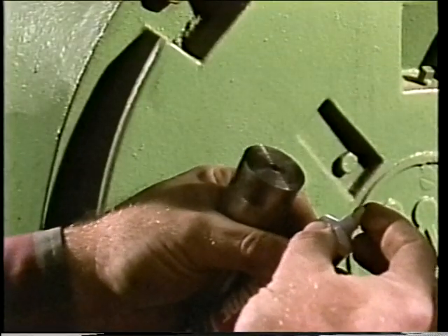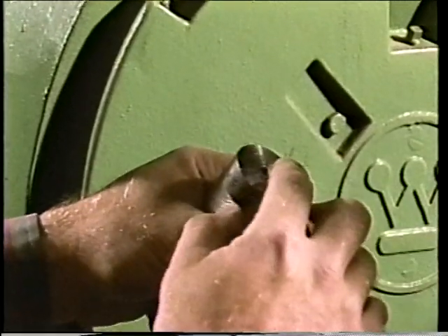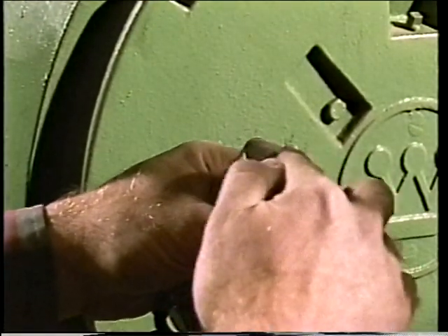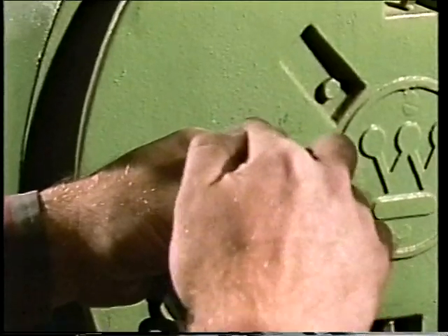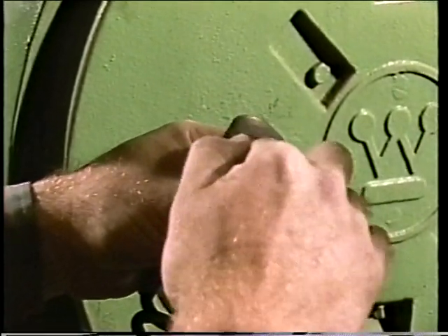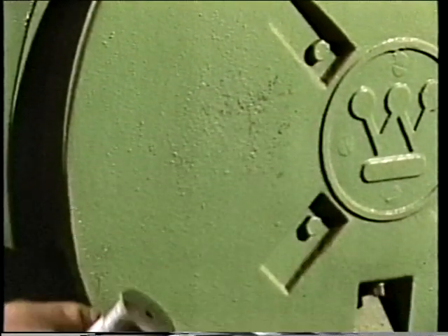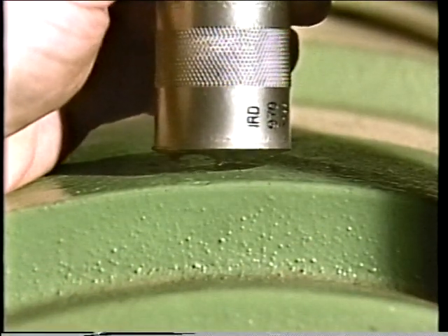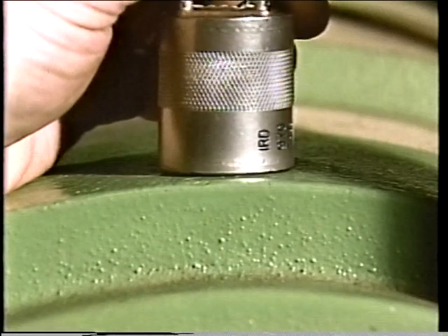In addition, many pickup manufacturers recommend using a silicone grease between the pickup and the machine being checked. This helps fill any gaps between the pickup and the surface of the machine to ensure that there is a large area of contact between the two. It also prevents the pickup from chattering on the surface of the machine.